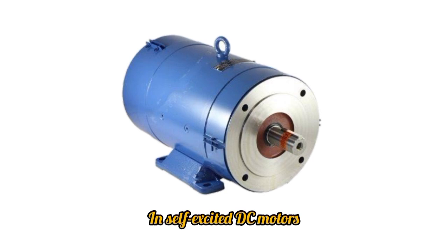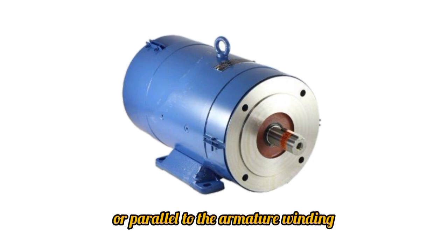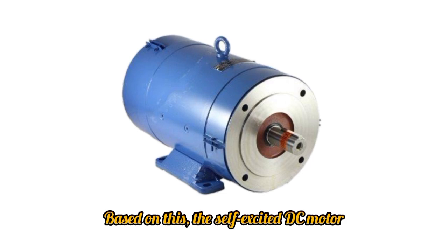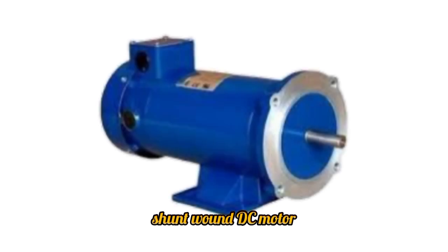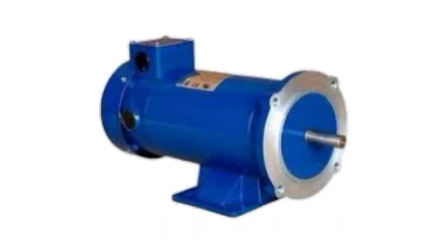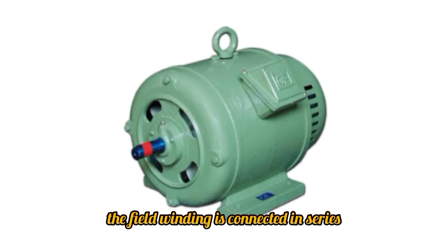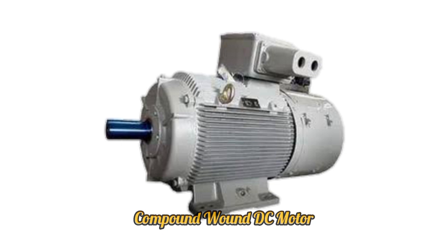In self-excited DC motors, the field winding is connected either in series or parallel to the armature winding. Based on this, the self-excited DC motor can further be classified as shunt wound DC motor. In a shunt wound motor, the field winding is connected parallel to the armature. Series wound DC motor. In a series wound DC motor, the field winding is connected in series with the armature winding.